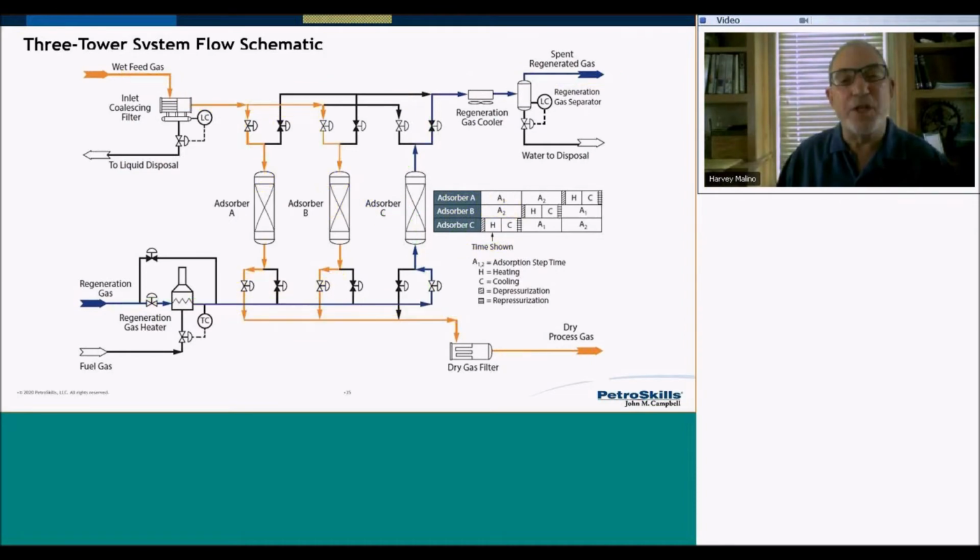So here we're using 3 vessels instead of 2. What determines whether you use 2 or 3 is generally a function of the feed flow rate and pressure drops. In general, CapEx generally rules, and people try to keep the number of vessels down to as few as possible.